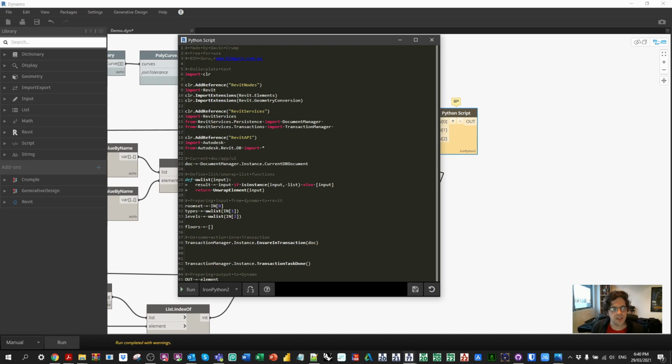And then we're going to begin engaging Revit in a transaction. So we're going to need to modify the model by creating floors. So we do need Revit's attention in this case in order to make this work. We're going to be building a fairly deep iteration statement here. So you're going to have to follow to some degree, but I'm going to try and explain it as I go. But the first thing we're going to do is we're going to call upon a big iteration statement. So we're going to work across our 3 lists of data, and then we're going to have to work deeper into our room lists essentially to get access to those curves at the very bottom, turn them into curve loops, join them together, and feed them into the API statement to create a floor with multiple curve loops.